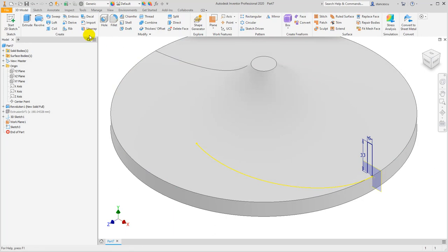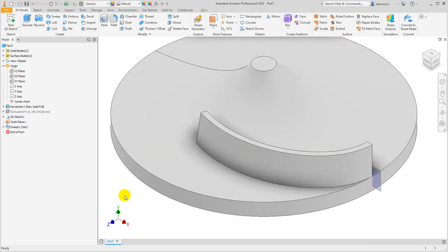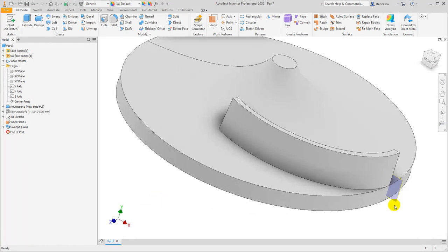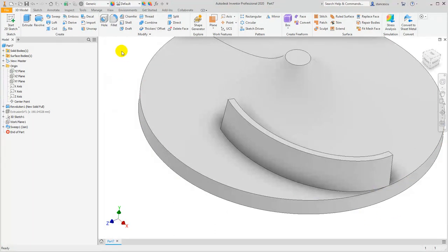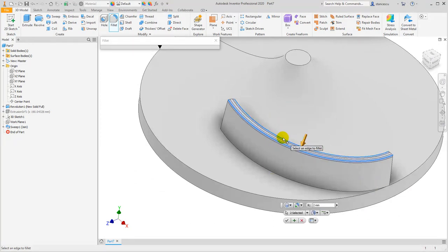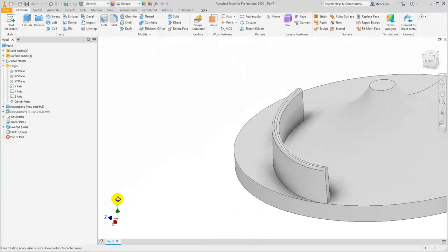Finish sketch, sweep, this was selected, and now we select this. Okay. Haha, this is the blade of our turbine. Good. Visibility, some preparation. 2 is good. Radius 2, because this is 6. 2, 2, 2. 3 of 2 millimeters. Now we say, okay, we have a blade.